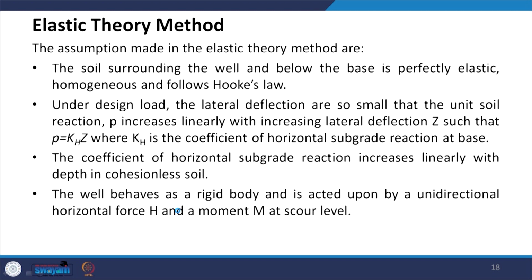That means if you increase the value of Z, the value of P is going to increase. Kh also depends on the type of soil. If you have sandy soil or granular soils, the value of Kh is normally considered to increase linearly with depth, and this coefficient of horizontal subgrade reaction increases linearly with depth in cohesionless soil, as we discussed.